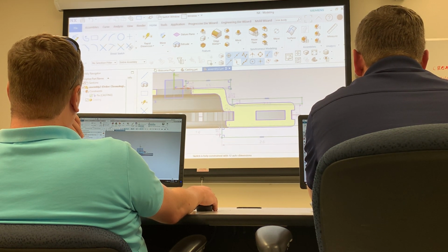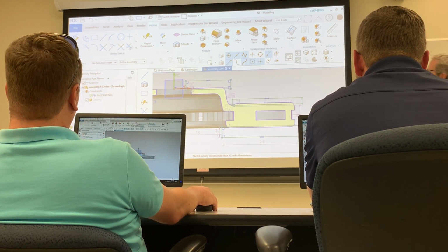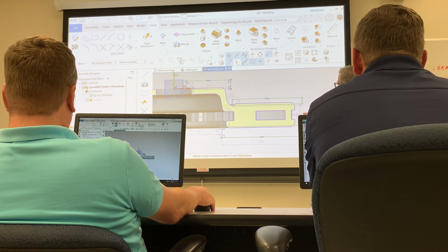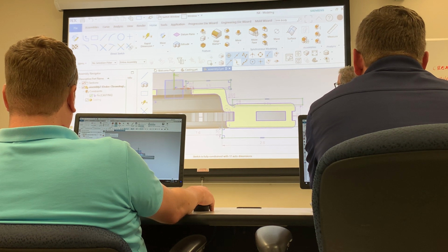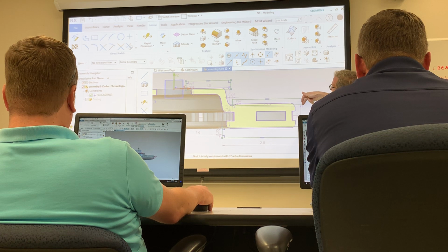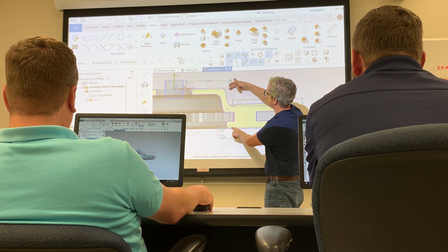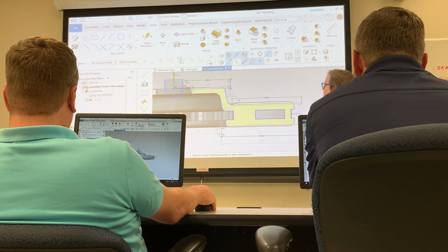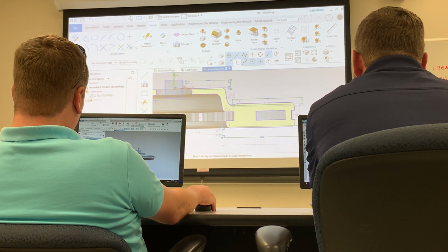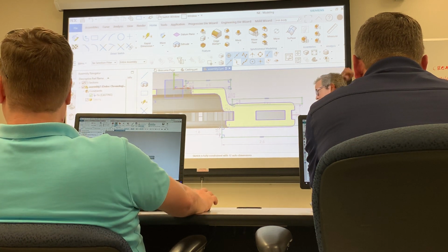Now, that's an awful lot of auto dimensions. For what we really only need 3 dimensions to control, right? We've got the 0.35 that's going to go here. We've got the 0.7 that's going to go there. Oh, look, I nailed it. 0.7 is going to go there. And then we've got, what is it, 1.25 or something up here to this surface from the box. All right? But we've got to get rid of the auto dimensions because if you don't tie them down, then they will move.